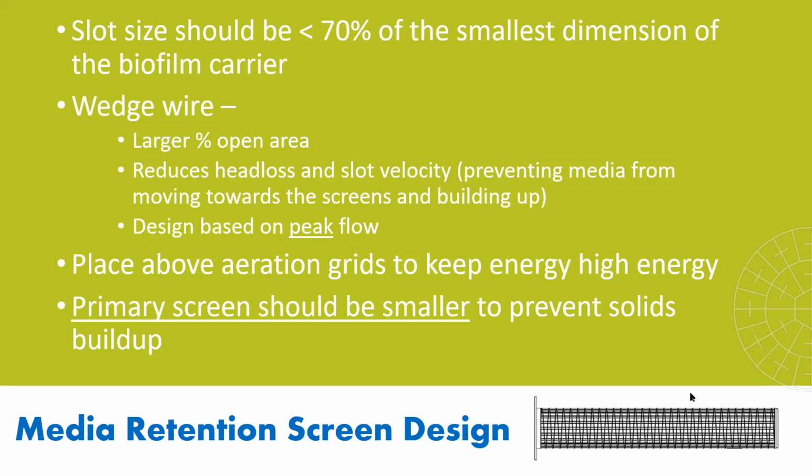We want to make sure that we're keeping the proper hydraulics within the tank. We want to place those media retention screens over the aeration grids to keep the energy from the aeration high around the retention screens to prevent any type of buildup, not just from MBBR media, but also of solids,